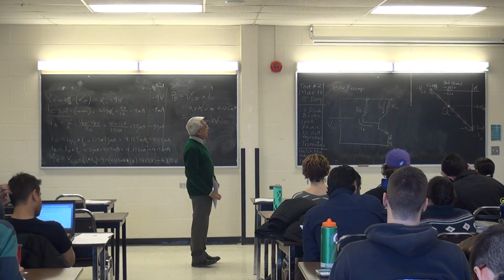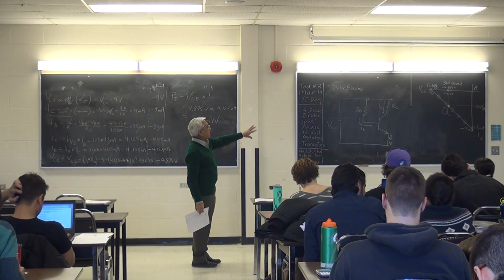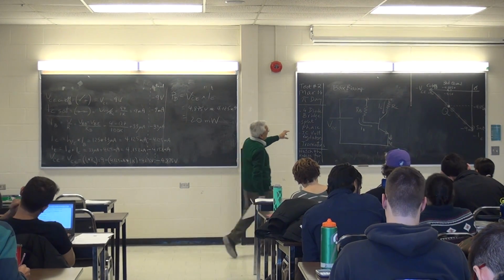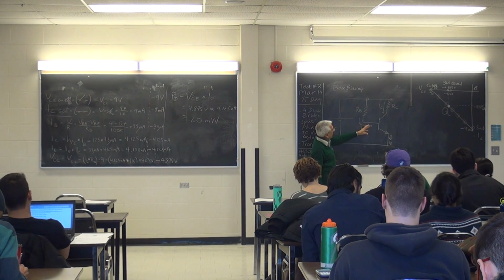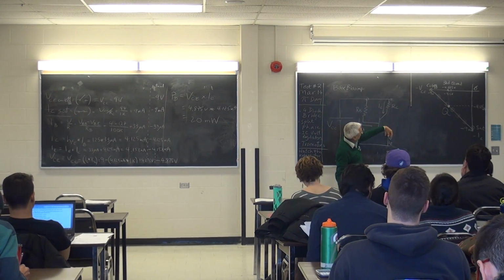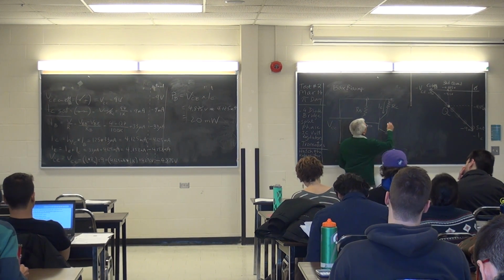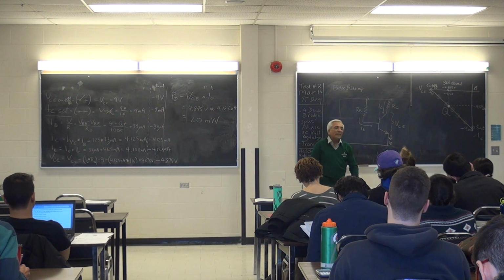So what I did was I did away with VBB and I merged VBB into VCC. I still need a voltage to provide to develop the base current, which is going to turn the transistor on, which will then cause IC to flow, which will cause a voltage VCE to appear in the circuit.